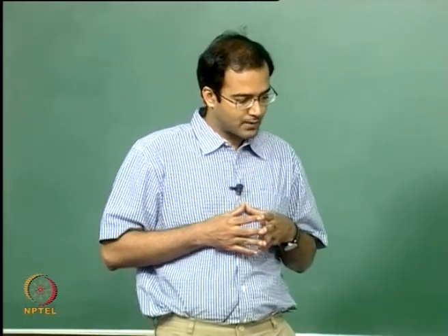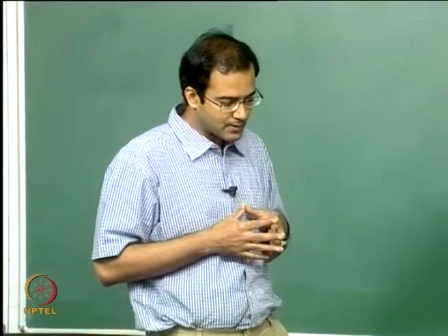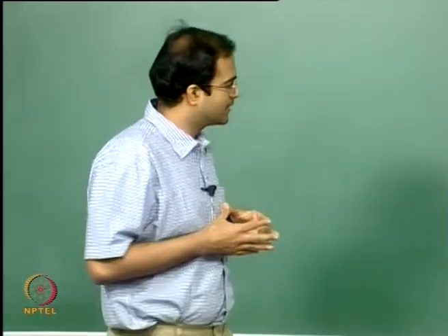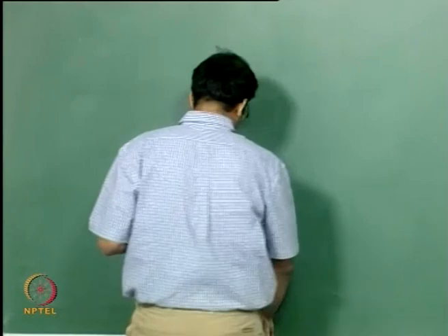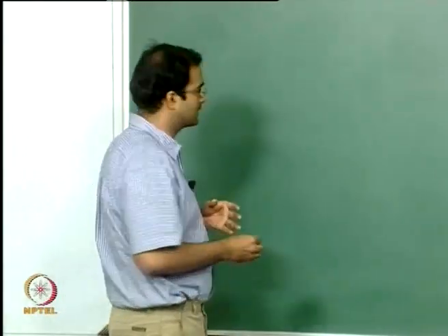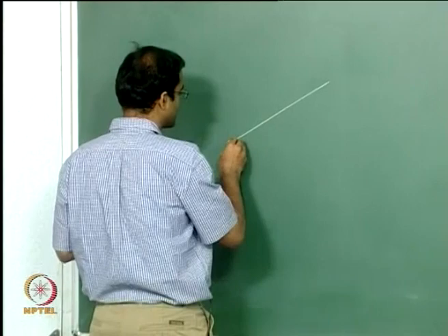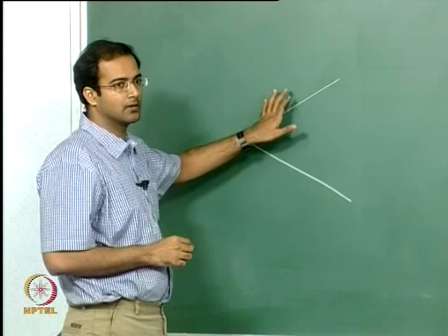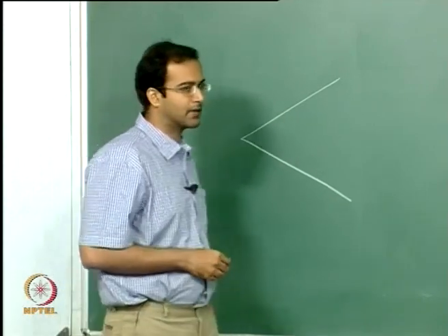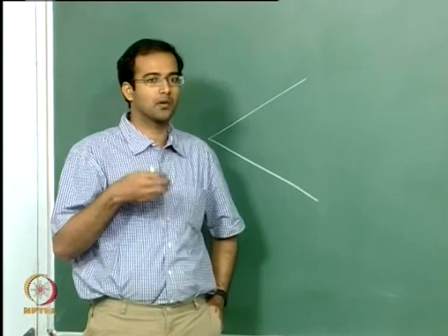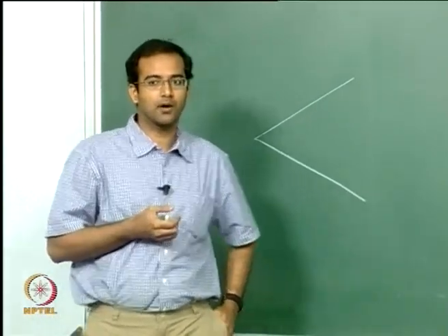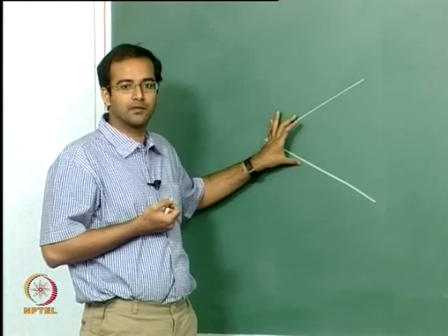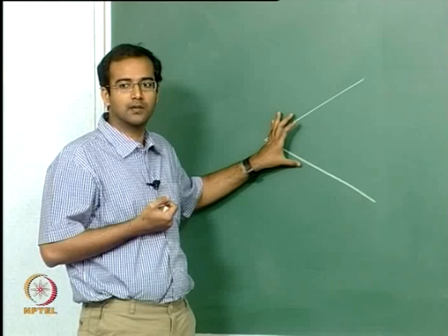Apart from that, the most generic case which we should have done is to consider a case of a boundary layer where you have transpiration at the walls. The Falkner-Skan solutions that we did considered no slip at the wall and no transpiration. In most of the cases you employ what is called boundary layer control. You want to control the boundary layer because it is sometimes detrimental, sometimes it is beneficial. So accordingly you may want to control it to your requirement.